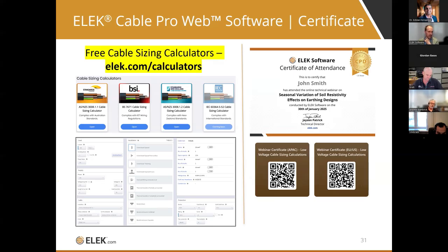They'll be slightly conservative. And for voltage drop, our calculator has a DC setting, and that DC setting basically ignores the reactance of the cable. So voltage drop will also be a bit lower for DC cables.